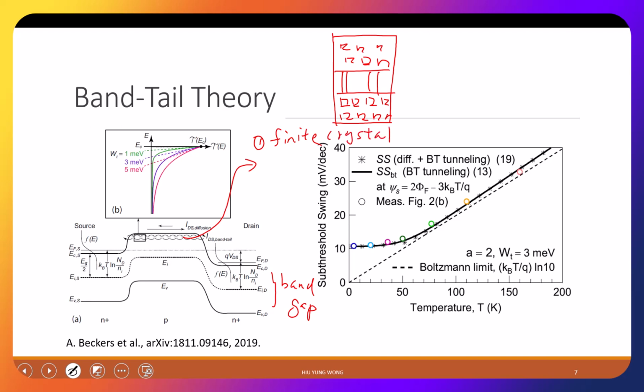So it won't be infinitely sharp, right? Second, you might have defects. When we calculate the band structure, we assume perfect silicon, right? So they might not be perfect, right? The third thing is you are at the interface between the silicon dioxide and the silicon. So it has an abrupt change. Definitely that is not the ideal condition that we have, right? So the final message is that I do have some states right at the edge. It's not abruptly sharp going from with state to no state.